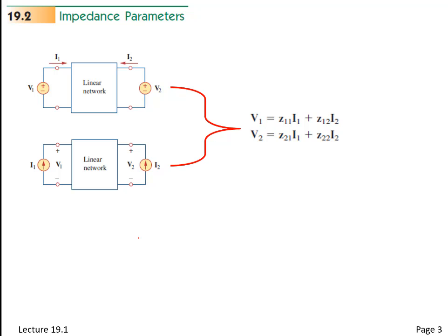Now these are vector equations, right? So the voltages here, that's why they're big and bold capital letters. These are vectors, and this is going to be a complex number possibly. Z11, whatever that is. All this is indicating right now is there is something that we're going to refer to as impedance, and there's four of them. One that relates input current and voltage, right, Z11. This term relates this to this.